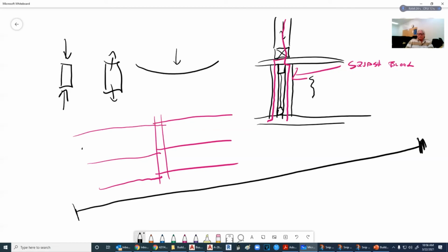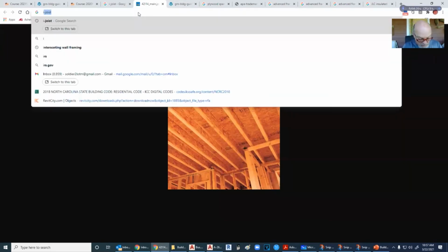Forty? Infinite. Now the question is, how long can you haul them down an interstate highway? Sixty? Fifty-three feet. Fifty-three feet is the maximum without a special permit. So if we had a house that was 53 feet long, we can order these. Now, I'm not saying it's going to free span all the way, because if it did, it's probably going to be about 60 inches tall. So if we go over to a span chart, let me go pull in the span chart.